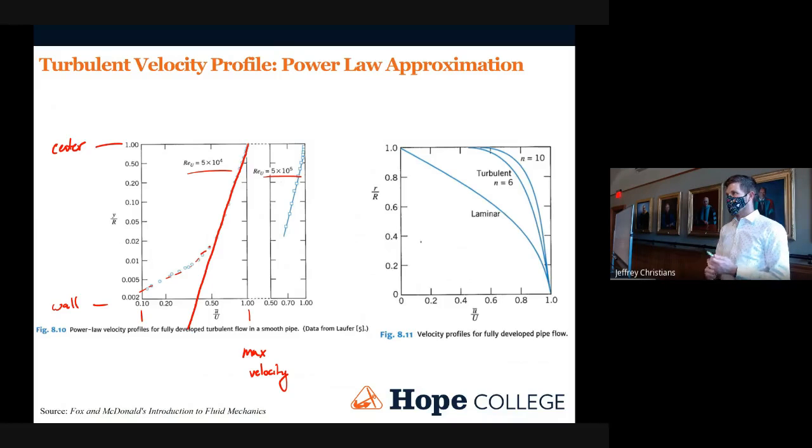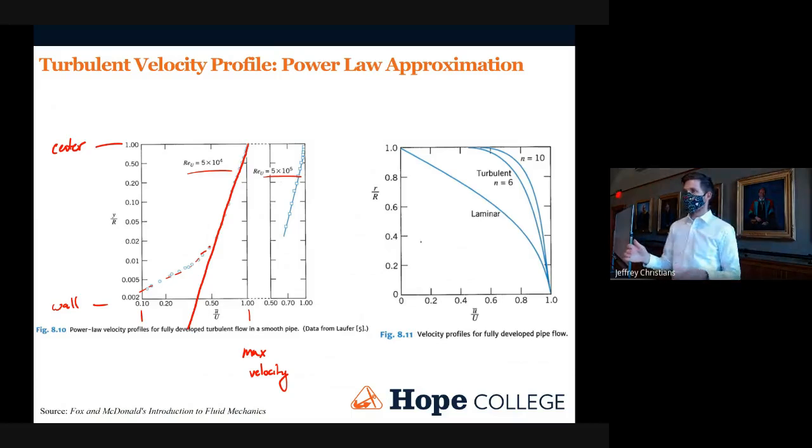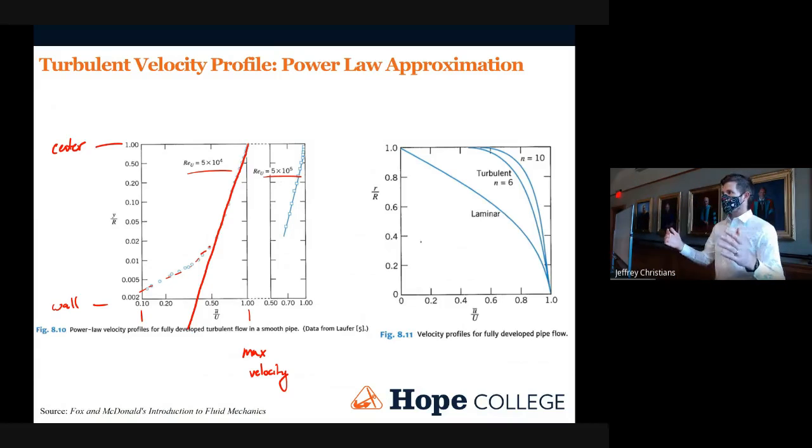This is totally different than when we were doing laminar flow models. With a laminar flow model, we can get a model built from the ground up. We can ask it any question that we want, and it will give us the answer. For turbulent flow, we have to make sure we're asking the right question to the right model, because none of them work everywhere. So it becomes a little bit of a different game.